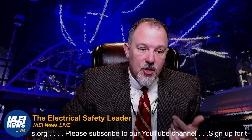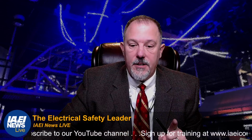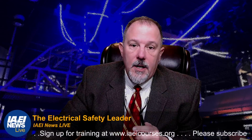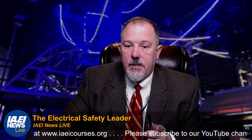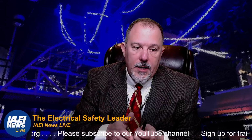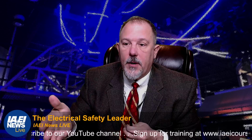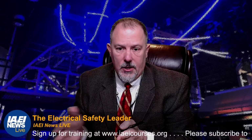So today I do want to make sure we get through all of our areas of discussion around lighting and the NEC. And hopefully you're getting something out of this series. We left off yesterday talking about the differences between HID circuit breakers, high intensity discharge lighting for lighting 50 amps or less, circuit breakers rated 480 volts or less, and those breakers that are marked for HID, what their capabilities are.